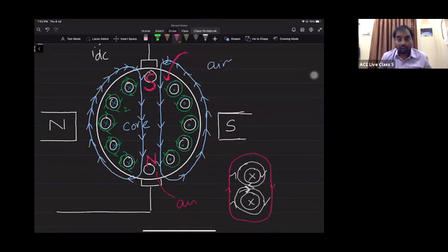Like this, we can have one more magnetic pole pair in the armature circuit. Again, this magnetic pole pair is also an electromagnet. Why? Because on the armature core, we are winding a coil, and through that coil we are passing a current. The current flowing through the coil will set up an MMF. That MMF will try to align all the dipoles inside, and hence that core will act as a cylindrical magnet. You can say this is one more magnet. Again, this is an electromagnet, right? Is it clear? Confirm.